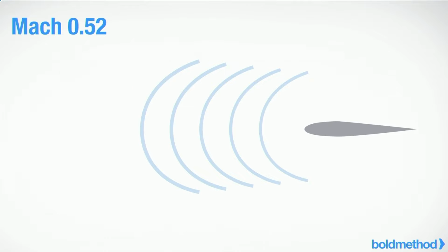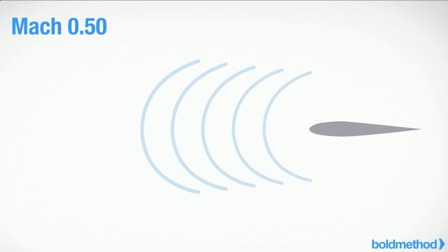We'll go back to the iPad, and if you tuned in on our last Pro, you've probably seen this, but it's a good thing to review. This right here is a basic airfoil. In this case, we're flying at about Mach 0.5, so half of the speed of sound. What that basically means is that the airfoil is moving slower than what air could transmit pressure waves. So for example, if I was to clap, the clap would move out ahead faster than the wing would move.